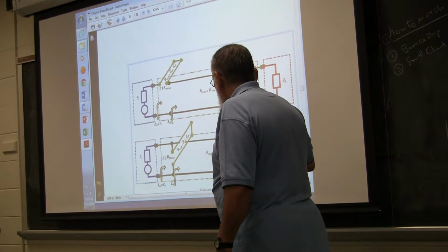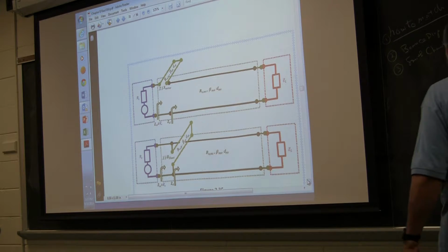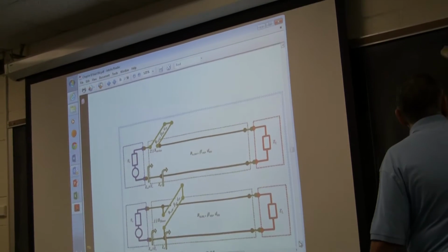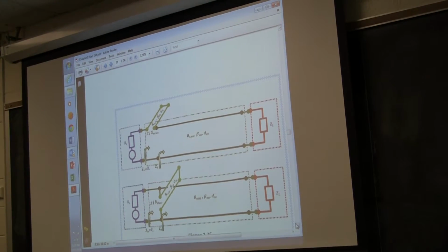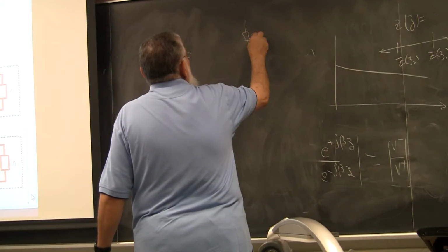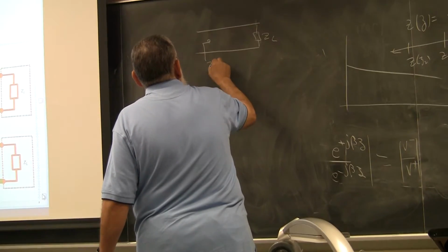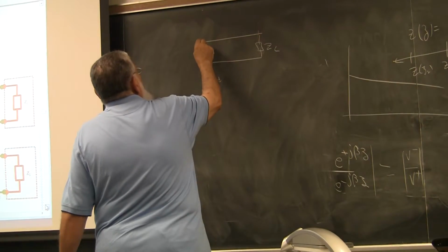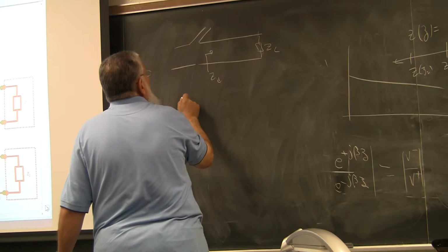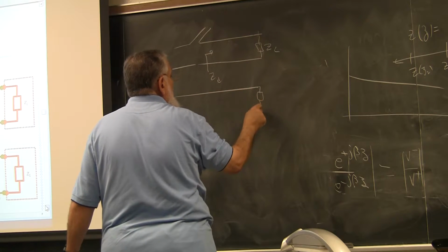But anyway, we can say that we have 4 options here. When you think about it, 4 configurations. Mathematically, you start with your impedance of the load, you move down the line until a certain location here, we call it Z sub D, and then I can add either a series stub or a shunt stub.